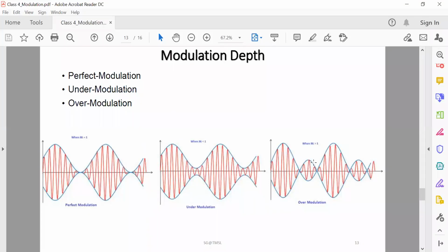Okay, and due to this distortion there may be some data loss. So over modulation is one of the reasons why amplitude modulation is no longer used to transmit high quality sound signals. Okay, at the transmitter limiters are included which prevent more than 100% modulation. So it prevents the 100% modulation. So that's why one limiter will be used.